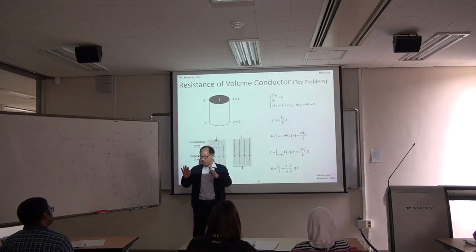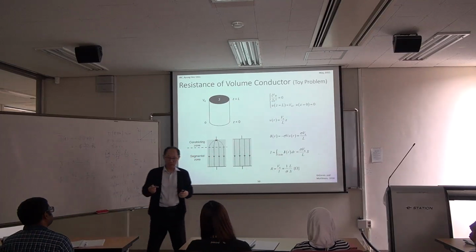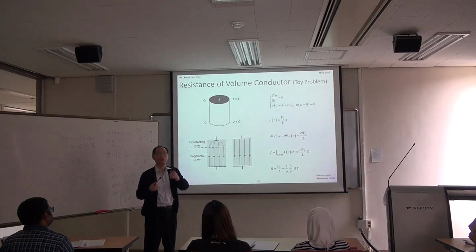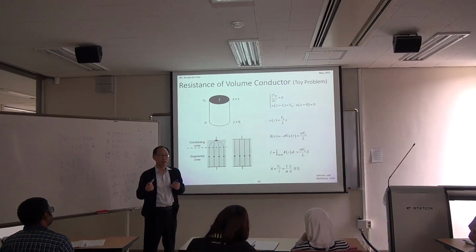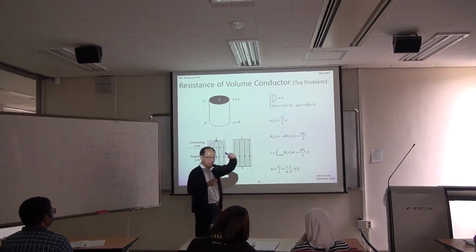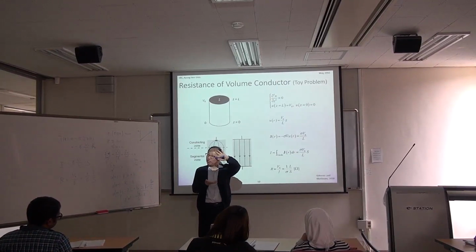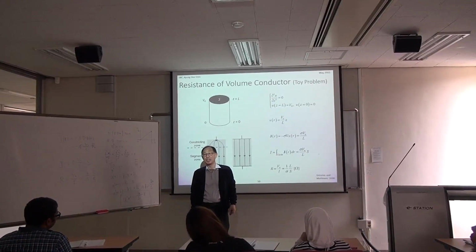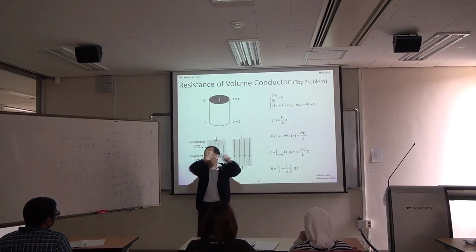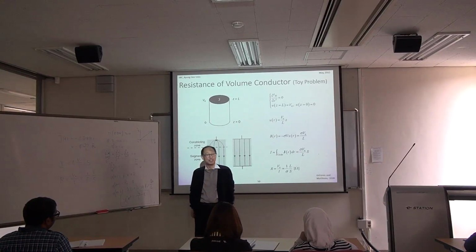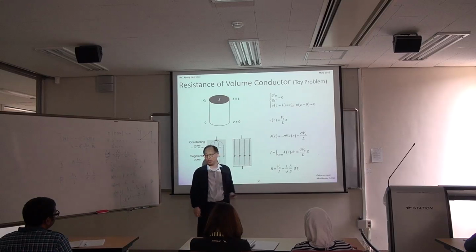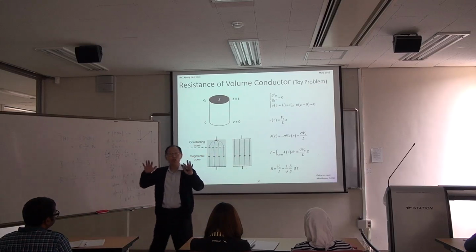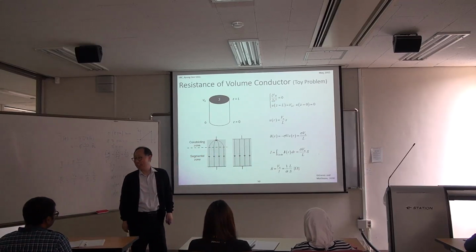If you don't know the position of the source, but you want to find an electrode configuration which will always give you the largest signal, even though the dipole position changes and moves around, then you should try to produce an electrode configuration which gives a uniform lead field.